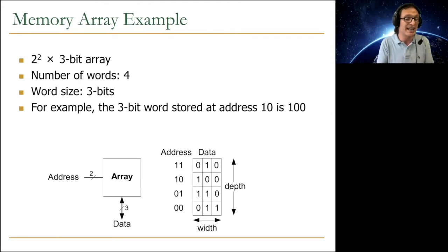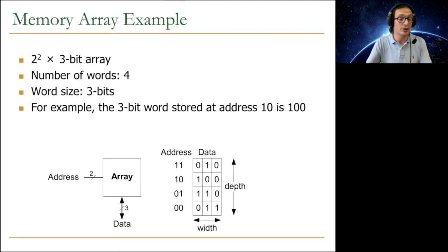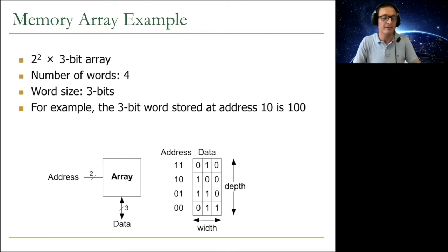As a result, your data width is usually small, let's say 64 bits, for example, or 8 bits. So if your array row size is 8 kilobytes, you need to select the 64 bits from the appropriate column based on a column address. So we will see this in a little bit also, but this is important to keep in mind. That's why we size the arrays to maximize capacity while getting acceptable latency.